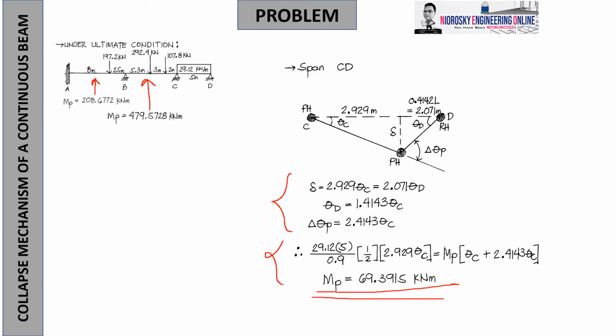So already discussed with you, but there was a question there? Because the load is being translated regardless if that is symmetrical or non-symmetrical. You always take the half of the load, as already explained before. Even if we place it like this, let's say the reaction is at the ends, but not the load, the treatment of your load is still taking the half.